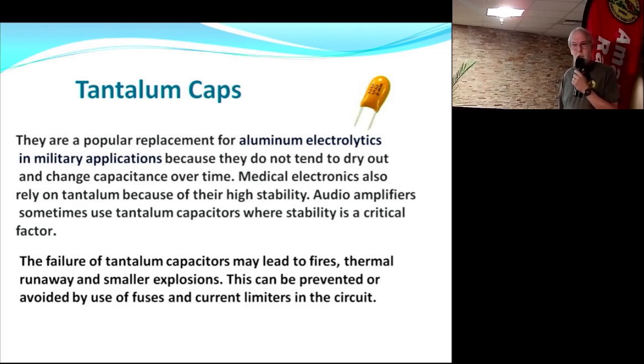An electrolytic, sometimes, if you're down below the working voltage, you can get away with putting it in wrong for a few seconds. Not going to happen with a tantalum. It's a mini bomb. It's just going to go off, which in some cases may not be in a circuit that you want to have near things that otherwise could go up in flames.